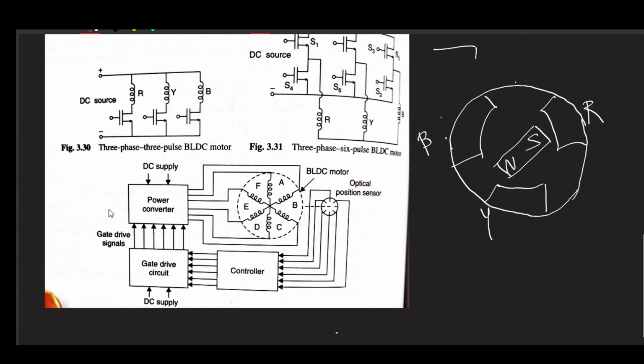If it is very fast, then your motor won't vibrate, but if it is very low, there is a chance that due to residual magnetism and other factors, I am not going into those technicalities because that would take a large amount of time for me to explain. But at low speed BLDC vibrate.